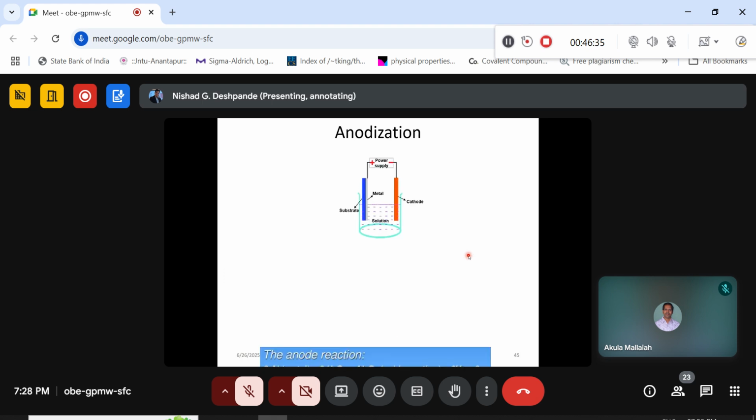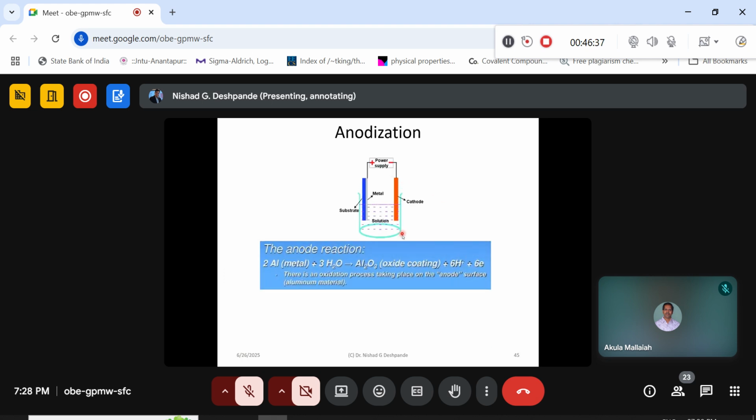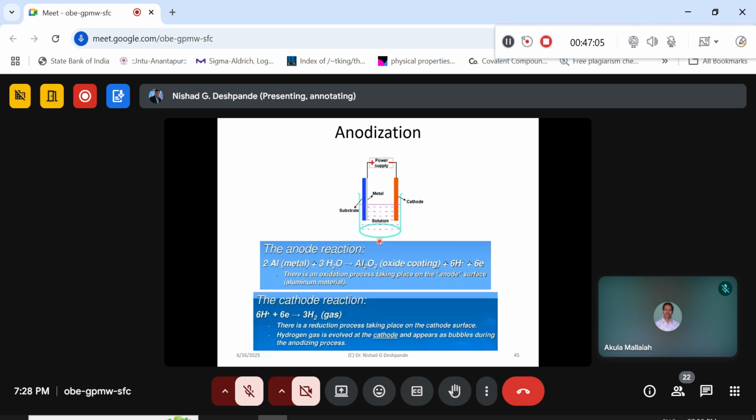Okay, just very quickly, you already have understood that in an anodization process, you have a positive electrode and a negative electrode, through which one can apply some voltages. Now the solution has ions inside, so forcefully one can make the ions move towards the respective electrodes. A positive ion will go toward the negative electrode, a negative ion will go to the positive electrode. So this is how one can have the oxidation process. So the silicon surface can be oxidized to silicon dioxide using electrochemical processes, particularly anodization processes here.